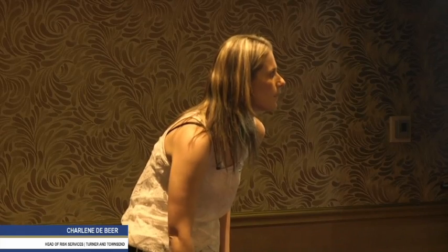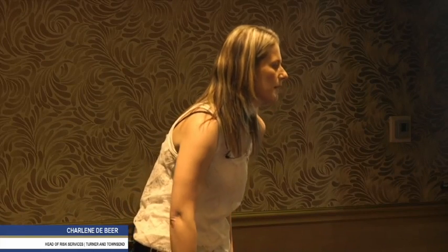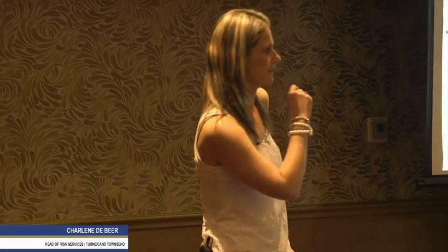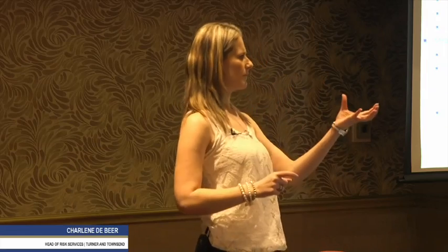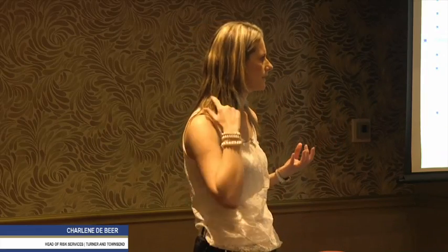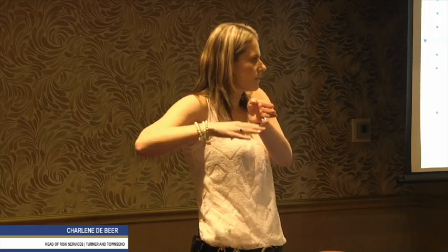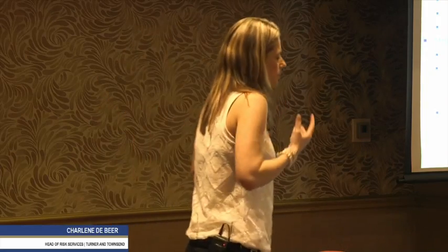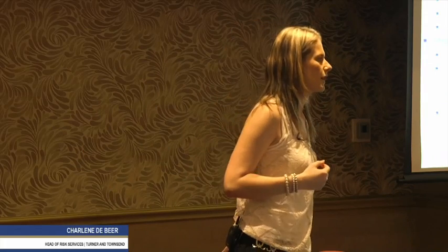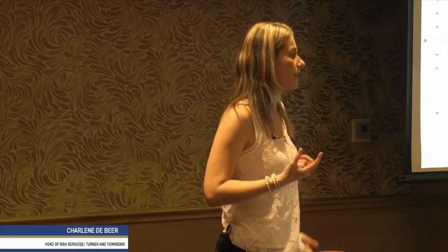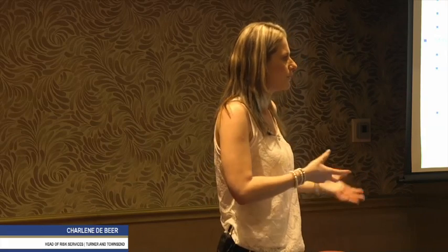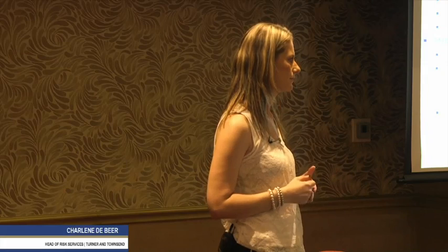As well as that, with a risk-loaded schedule, I'll pick up how much float there is. So if I say it's a 10-day delay and there's 5 days of float, it will just push out that activity by 5 days. It won't keep the 5 days float and then attach another 10 days. It's got a lot of logic around it, saying, you're telling me it's 10 days, I've got 5 days in my float, it's only going to impact 5 days. But if those 5 days don't have a direct knock-on, it's a parallel activity and it stops there, and it's not driving your longest or your critical path, it also won't move your date. But if it is a driver, it will shoot out your date. By how much, I won't be able to tell you until we do a physical assessment and see how accurate it is on that schedule.